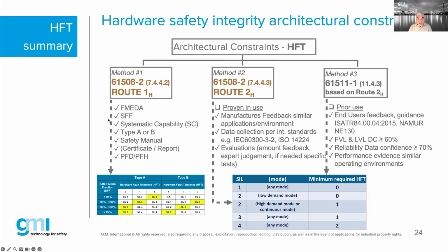And in that section, this is here -2, which is shown over here, the hardware section. That means a specialist will make an FMEA, which stands for Failure Mode and Effect Analysis. They have to determine the safe failure fraction to come into the left column. In which row do we have to look to comply to a certain SIL? With what minimum hardware fault tolerance will I need?